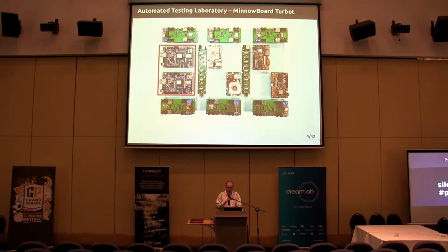So on your left, we've got two MinnowBoard MAXes. These single board computers serve us as target devices for x86 architectures. They can be used as both 64-bit and 32-bit target devices for Intel architectures, and switching is as easy as replacing the UEFI on board. In the middle, we've got two Odroid U3+, which are the most common, most basic target device for the Tizen Linux distribution, not only for our profile, but also for TVs, mobile, wearable, IVI, and so on.